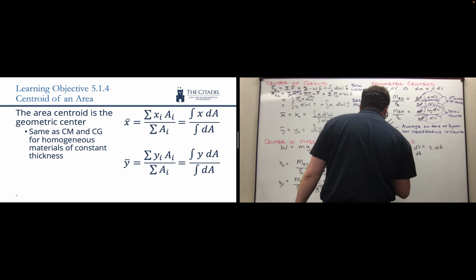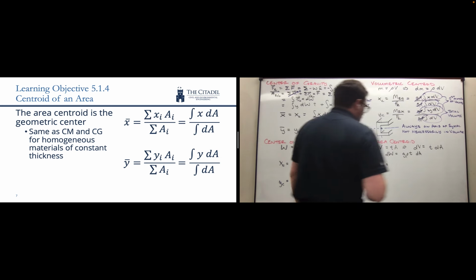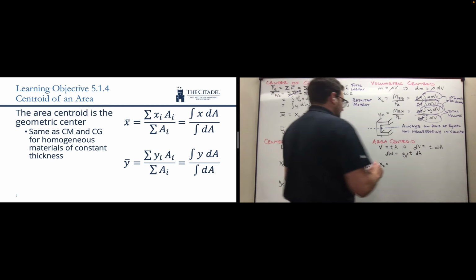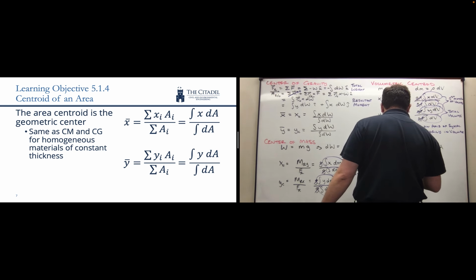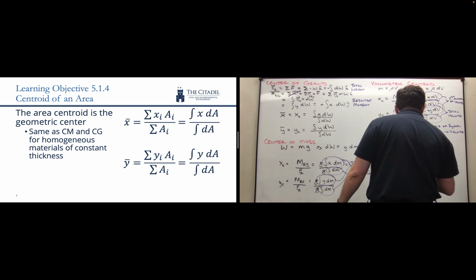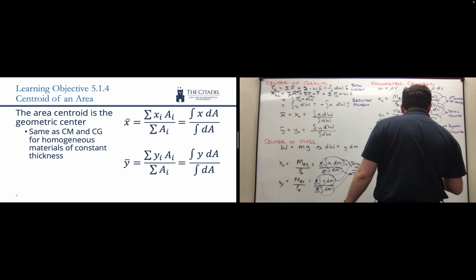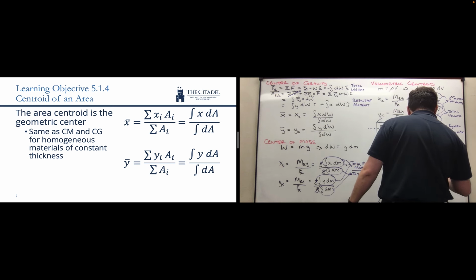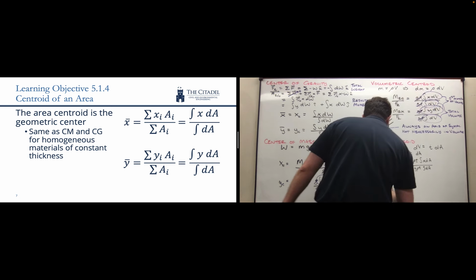So this is actually the thing that we'll spend time calculating, where our x centroid is going to be equal to, still, it's an equivalent system, so our resultant moment about the y divided by the resultant force, just that in this case we're going to have g and rho and t, the integral of x dA divided by g and rho and t, integral of dA.